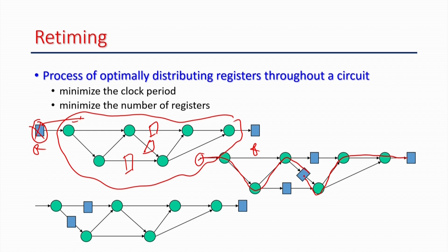So, what retiming does is move the registers in the circuit so that it reduces the combinational delay. But we have to keep in mind that certain rules are there. We can move a register from input to output only when both the fan ins have registers. Or if I move a register from fan in to fan out, it has to move to all the outputs, then only the functionality will remain the same. Okay. So, this is the core concept of retiming, and you can understand that given a bigger circuit, you have a lot of options, a lot of possibilities for moving registers, and the circuit is not just 8 or 10 gates with only 2 registers.